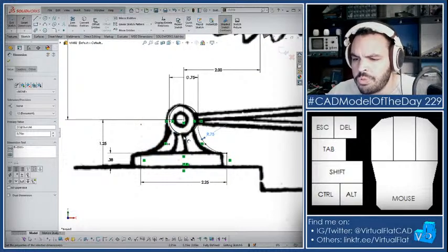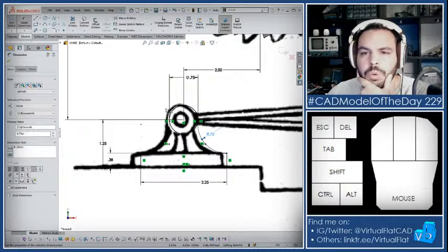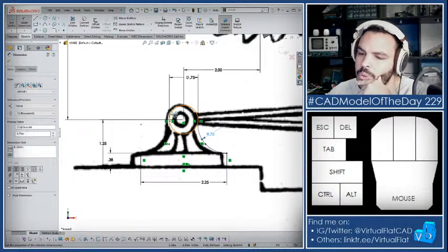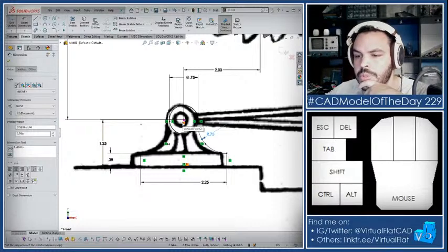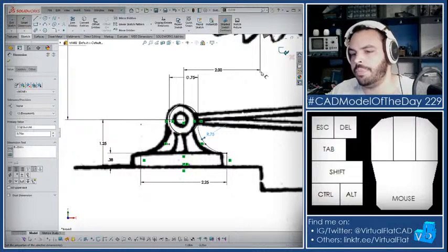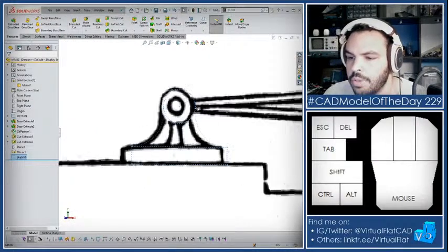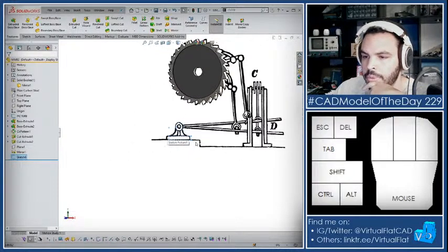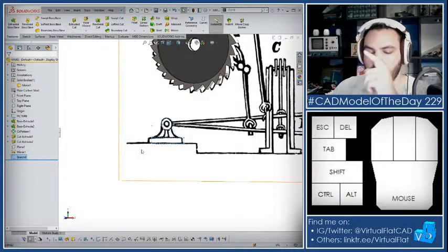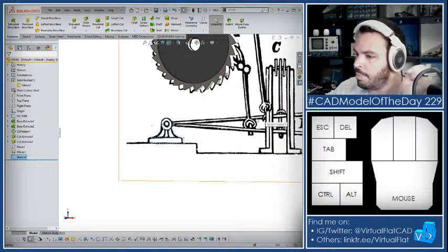Right, so I can trim this, or I can just leave it as multi-contour. Yeah, there's really no reason to leave it as multi-contour, unless I really wanted to put a lot of details in these blocks. Yeah, let's try it out. You know, I'll just leave it. So typically leaving these overlapping contours can lead to some problems, but you know, we'll see how that works. So before I extrude this, I'll save, but